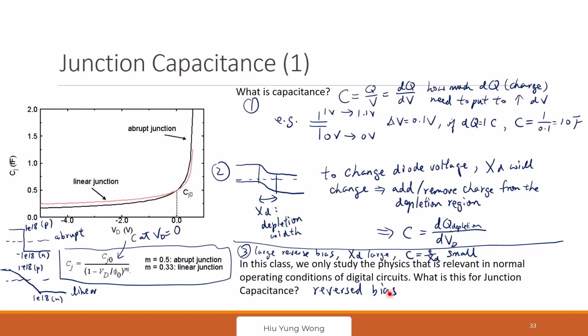If you don't understand, you can still just use this equation. But I think that will help your interview and help you really understand why I'm using this. The last thing to take home is that this is how you calculate the junction capacitance. You have both forward and reverse bias junction capacitance, and reverse bias is smaller.